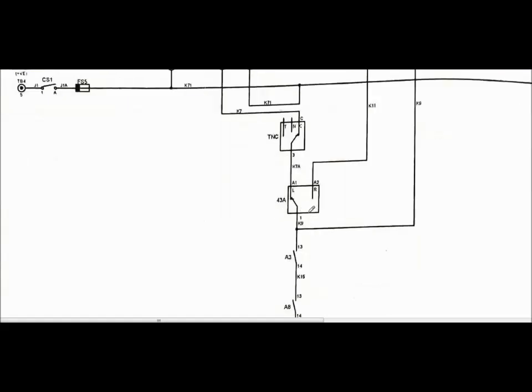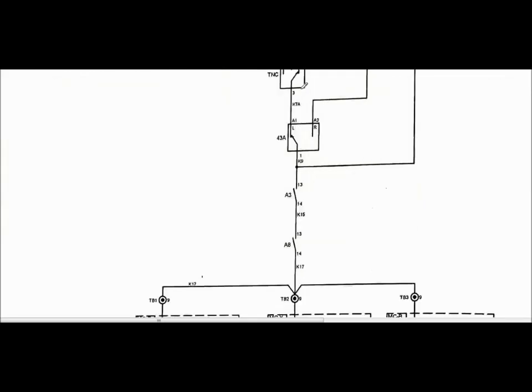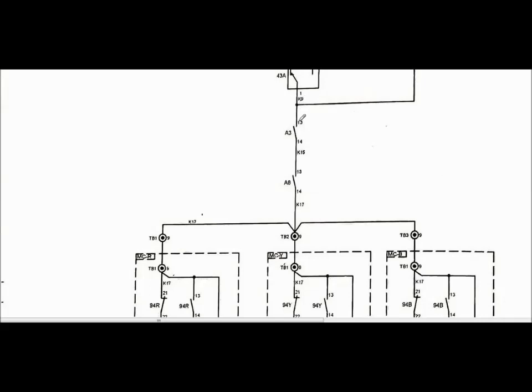For local operation of the circuit breaker, this selector switch must be in local position, and from the trip neutral close switch a closing pulse should be given. As soon as the closing pulse is given, the DC will come from K71 to K7, and from the trip neutral close switch via the local remote selector switch to K9. Whenever it comes to K9, then via these two contacts, which are in NC position as gas pressure is under normal condition, it comes to the TB29 of each phase.